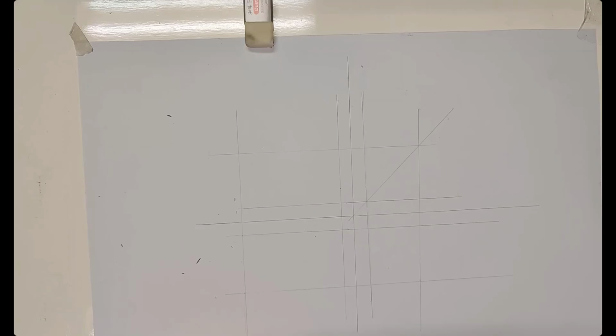So we begin at side view. Do not start at front view. You cannot start at the front view because you cannot know where the point is that has the 45 degree cutting plane. So the best view that shows the profile, remember when you do SolidWorks modeling, the base profile modeling approach, the base profile is actually a cutting of 45 degree. We make it with a bounding box, and the base profile, a cutting of 45 degree, can be clearly viewed from the side view, from D. You can see the direction is side view. So you start at side view.